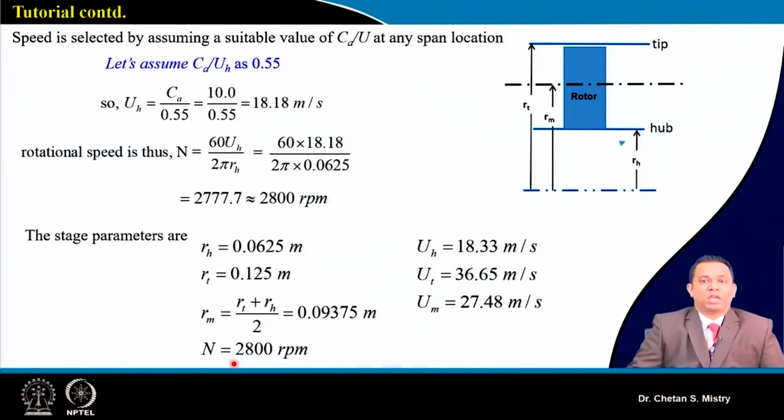Maybe the end user will say they have a motor with a rotational speed of 3000 rpm, and you can straightaway take that as the rpm. As we have discussed for the design of the wind tunnel fan, there will be a certain amount of slip. So the rated speed will be say 1440 rpm, 2400 rpm, 3000 rpm, but we will not get exactly that number, maybe slightly on the lower side.